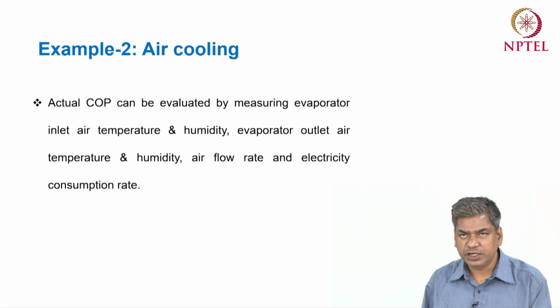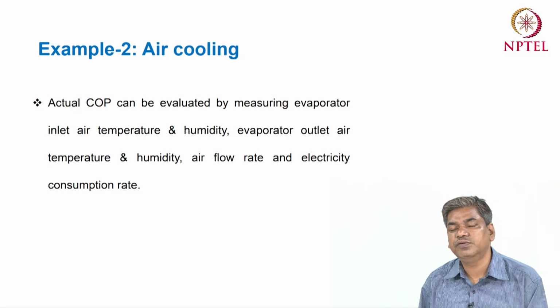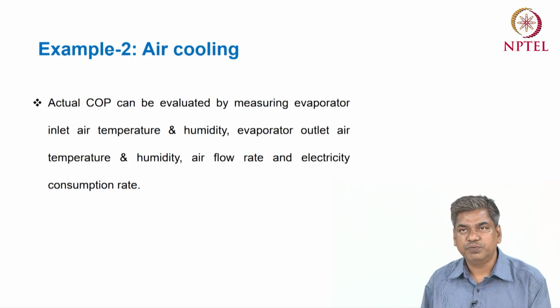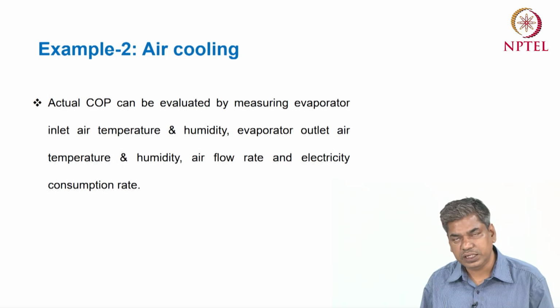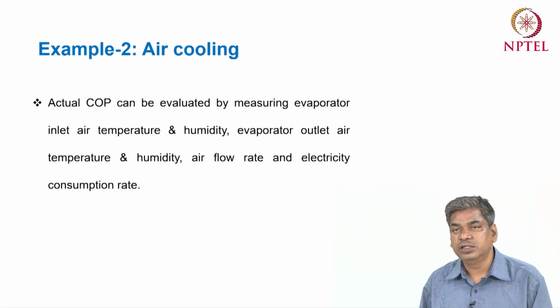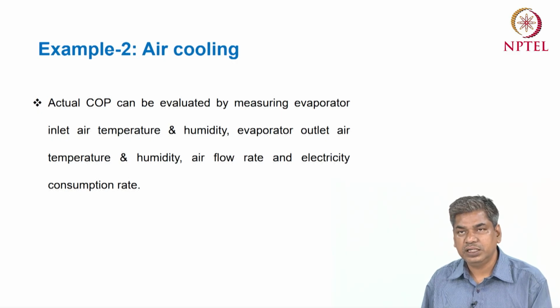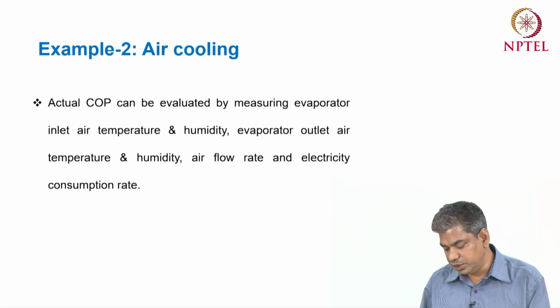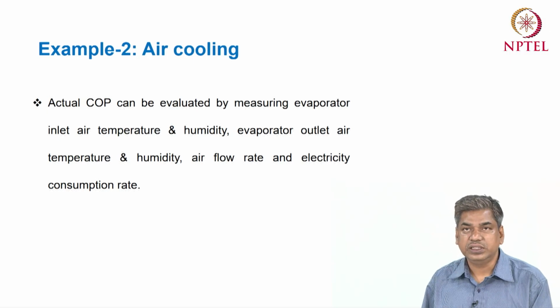Similarly, for an air conditioning application, if you want to estimate the performance, you need the air inlet and outlet conditions, like the air inlet temperature and air inlet humidity, similarly the evaporator outlet air temperature and outlet air humidity, and also the air flow rate and the electricity consumption rate. These are some of the parameters you have to measure, and based on that you can evaluate the actual COP for this air conditioning system.